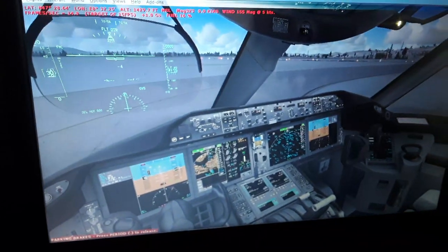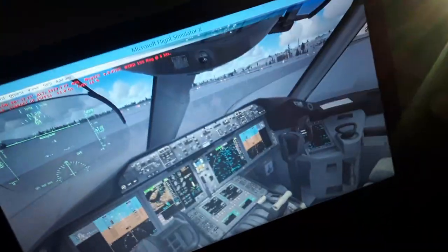We have also the HSI with the magnetic heading and track, the integrated standby display. The integrated display of the flight plan. You're going to see later we're going to create a flight plan or a flight path route, which is going to be displayed in the HSI. Also in the navigation display, we have the horizontal and vertical profile of the aircraft as it flies, the flight plan, and also the terrain and weather reflections from the weather radar.